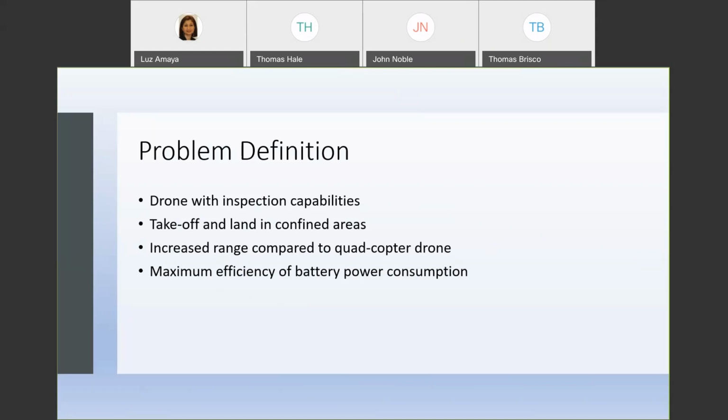In regards to increasing efficiency at takeoff, it's possible to attach the drone to a rail system and use an external system, such as a launcher, to propel the drone into flight. The drone may have its wings folded at launch to maximize the aerodynamic efficiency and minimize drag. And combining the range advantage of the fixed wing drone with the takeoff and landing capabilities of a quadcopter drone can drastically increase effectiveness for all types of users.